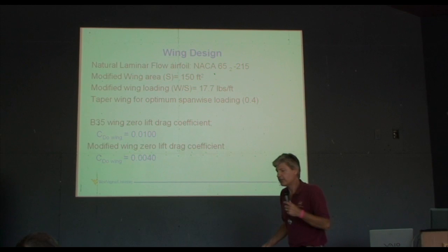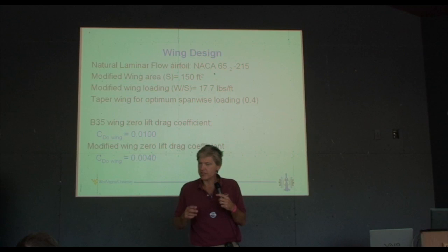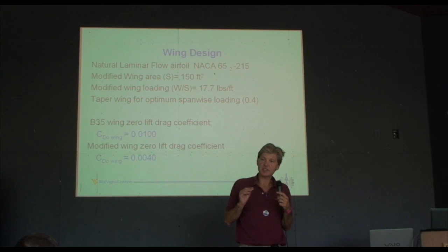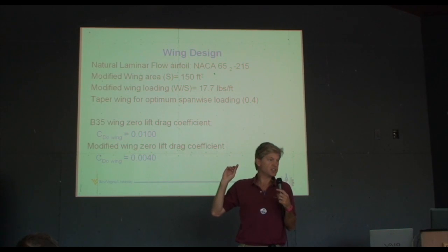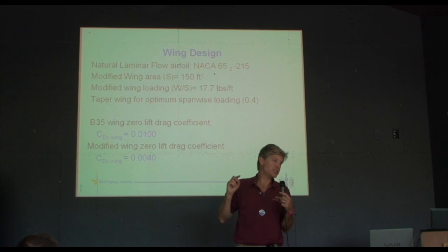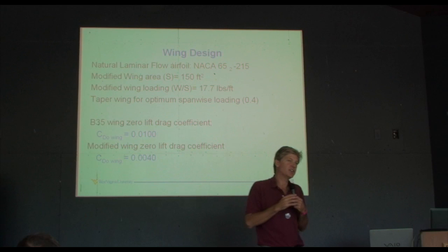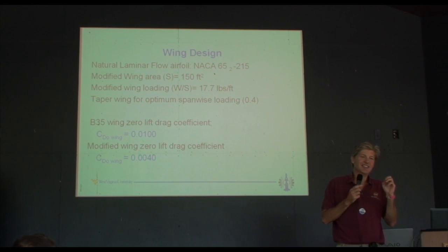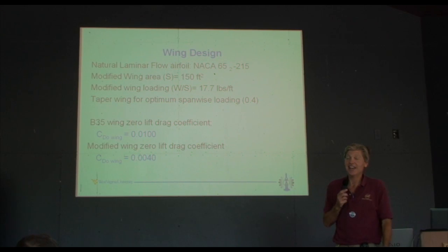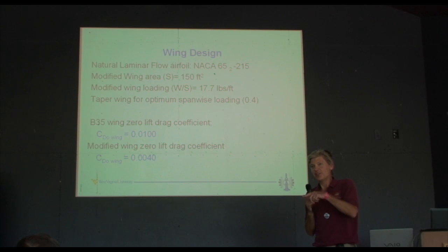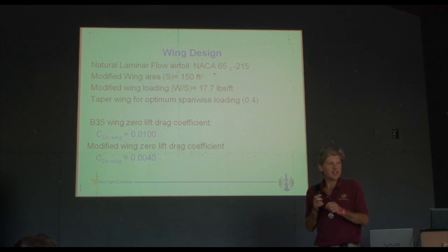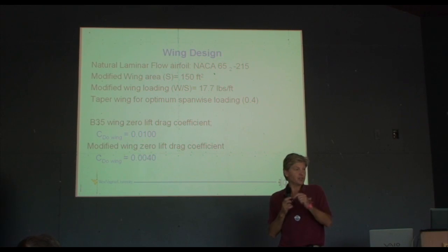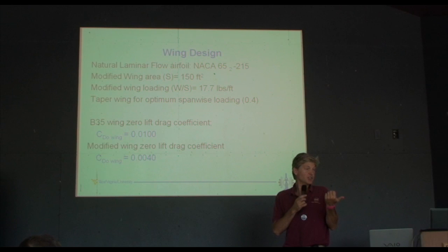And a little bit about airfoils. NACA has a 4-digit series, a 5-digit series, and then early on the 6-digit series, and then there's a 7-digit series. You can recognize the 4-digit series because they have 4 digits, and the 5-digit series because they have 5 digits. Actually, the 5-digit series, like the 23015, that's an old airfoil. You'd be amazed how many airplanes use the 23 series. One that I was surprised at, the C-5 Galaxy, uses a 23 airfoil.